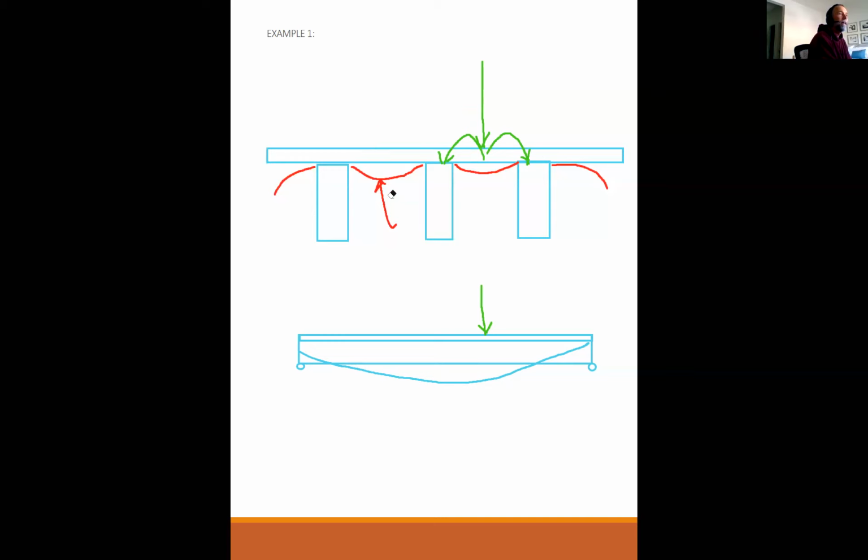Okay, and then, because I'm sure lots of folks are getting confused by this, the other part about this is when I design the one-way slab, my flexural steel is going this way for the positive moment, and it's going this way for the negative moments, because the slabs have positive and negative moments. But the beam reinforcements show up as dots because your rebar is always going in the direction of your span.